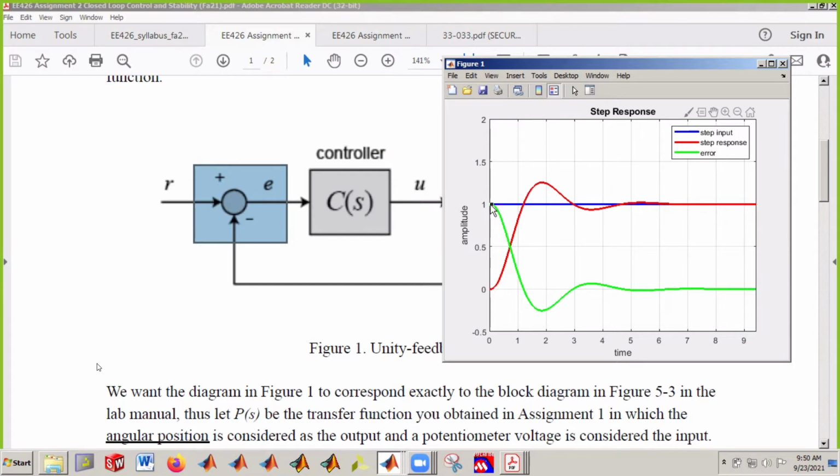Because this is where they are furthest apart. The motor is starting at 0 angular position, and this is at 1, whatever this 1 means, right? Remember, we can always scale this, so 1 does not mean exactly 1 degree or 10 degrees. It can be anything, as long as we scale it. But we can also change the initial condition and make this smaller. Well, you see, as the system has time to evolve, eventually the error converges down to 0.